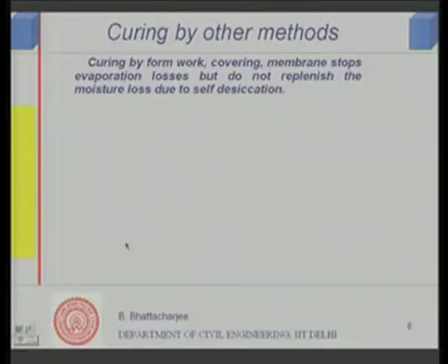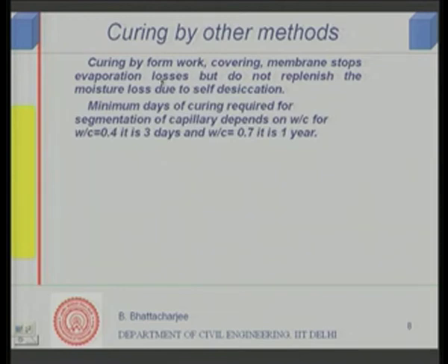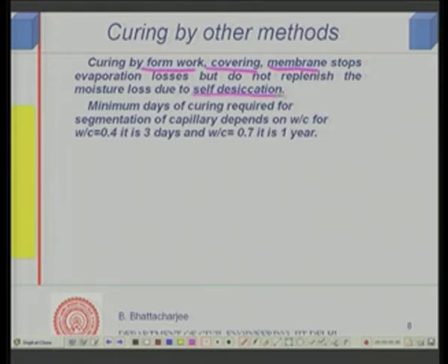I mentioned to you curing by formwork, covering with membranes, and all this. Covering with these coverings, membranes, formwork, all this actually stops evaporation loss, but does not replenish the moisture loss due to self desiccation. So, they can be as good as the moist curing, right. Okay. So, I have mentioned that already and explained.